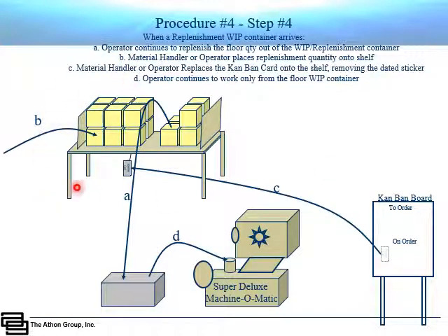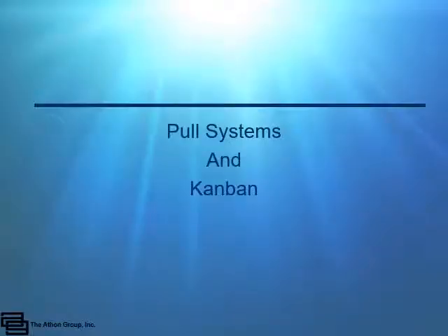Once the reorder material comes back in, we put it very carefully over to the left-hand side, and we keep working out of the right until such time as we exhaust all those boxes. Then we start working out of the left. But when we start working here, you'll note when this gets empty again, we'll rehang the card to order half the quantity. So those are just a few examples of Kanban systems that I've used in the past.